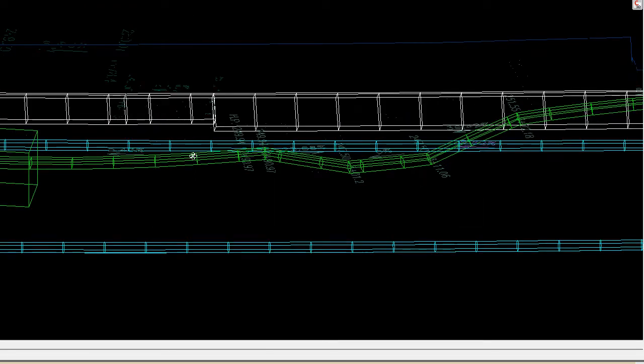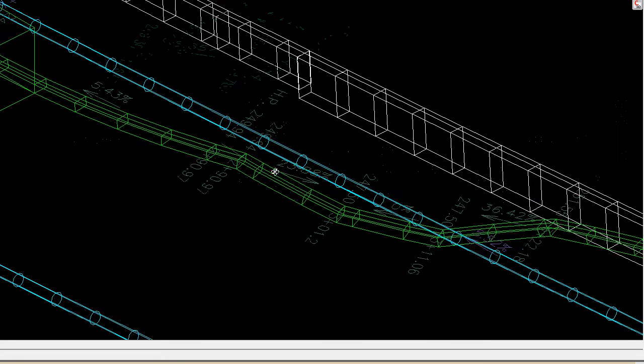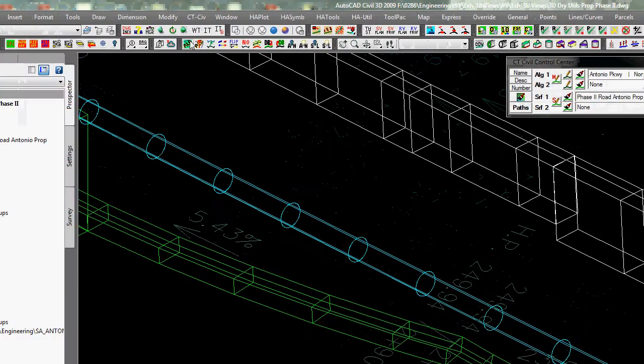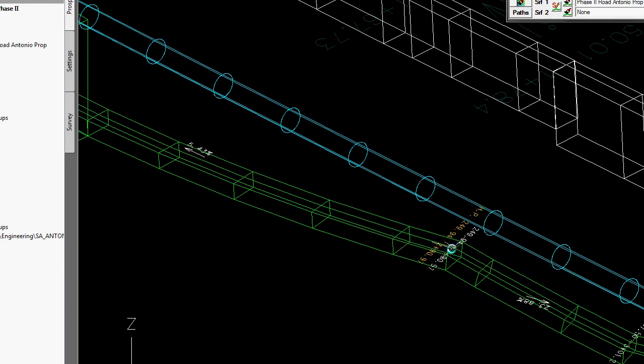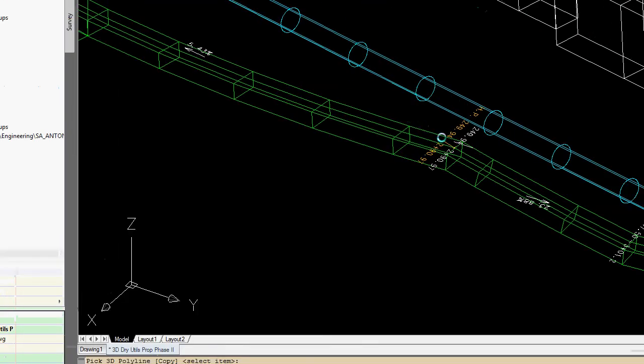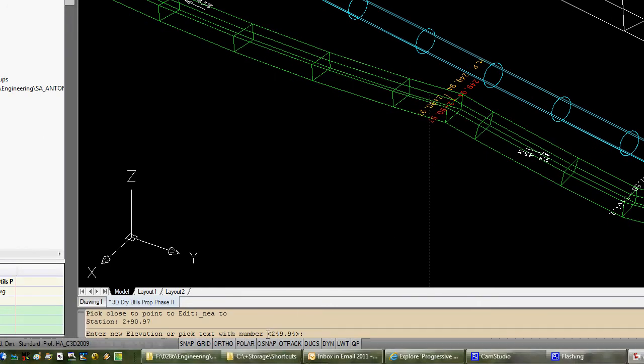Okay, I'm going to edit. I messed up the snap. Let me do that again. Okay, edit. I type E, by the way, for edit. Picking nearest, find the closest PVI, which is that guy, and it gives me the default number that's already there. I'm going to lower that by a foot. So basically at 250, I'm going to say 249. Okay, so it's a little less kinked.